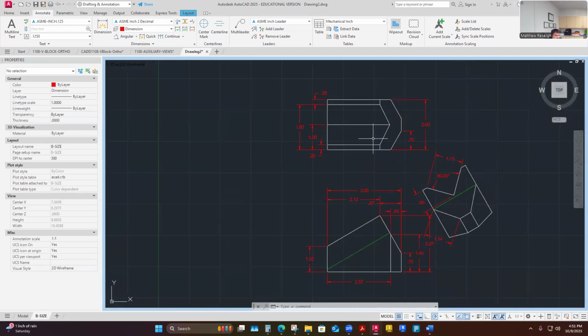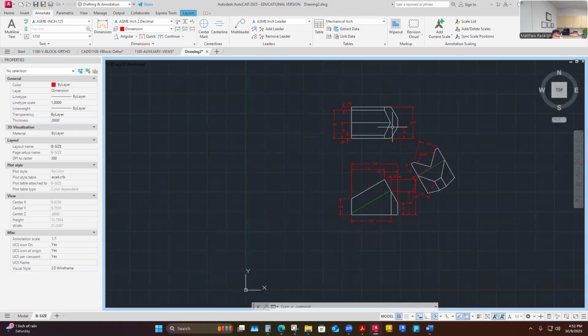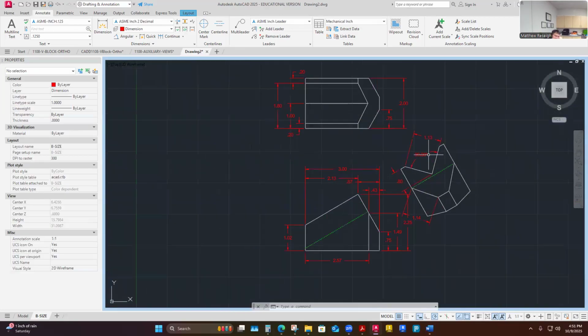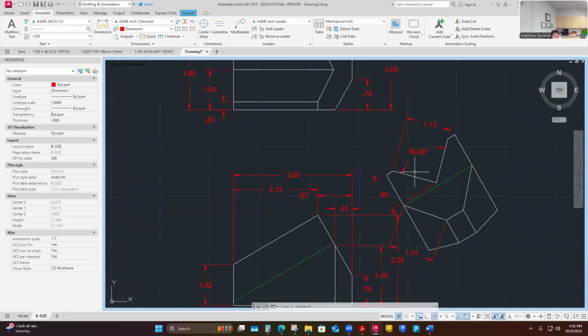Go back to, okay, I've done this surface, I've done this surface. What else in my top view? So I've only really dealt with this surface, the V surfaces, and that surface. And now I've got to think about this surface that I see in my top view. And what are its dimensions? That's definitely why we did the auxiliary view, is this surface. So I'm just going to walk over to it, decide if I've got its side lengths figured out. I'll just start from over here.